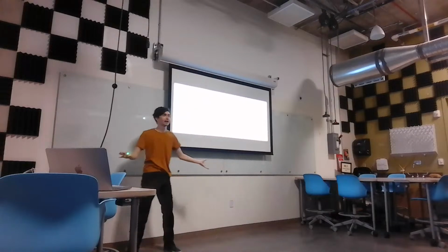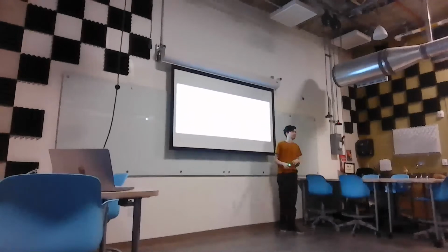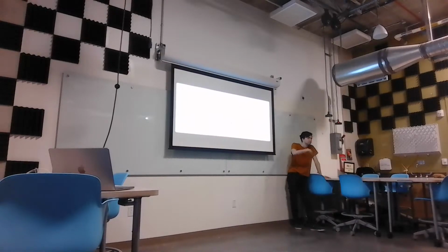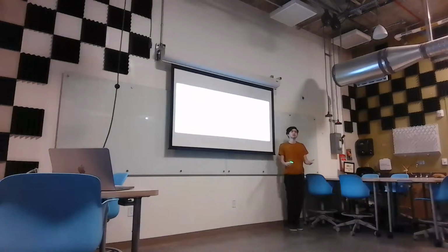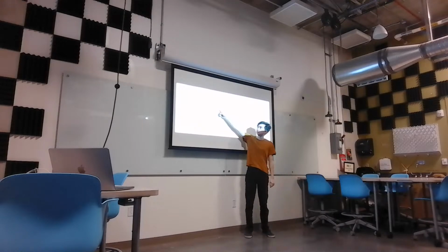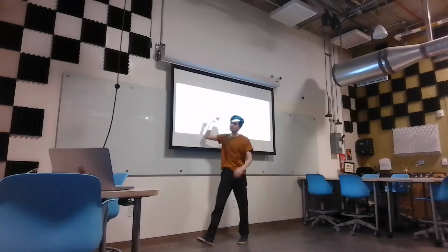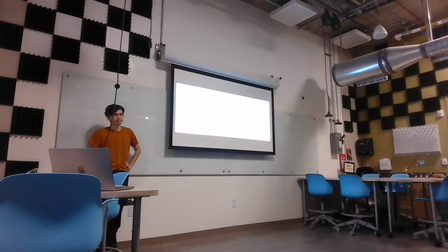We've got a half pitch here, guys. And what's this? Oh, look. This is called current shunt. Because, of course, if we're trying to achieve a target current, we have to know what the current is in order to make adjustments. We know its resistance, we measure the voltage across it, now we know the current through it. That's how you measure the current. There's some cool little amplifier here that converts that to a nice voltage for us to read. Plug that into the ADC on the microcontroller and box it up. Should be pretty easy, right? Well, let's see how this one went.